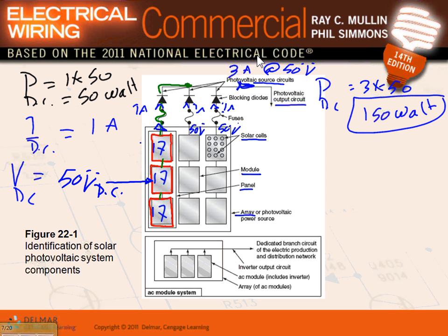Any question? William, does it make sense? Rob, my friend? Okay, now we'll get back to this, how to size it and disconnect it and all this stuff. And I'm going to get back, Dustin, to your question. There are two inverters, guys. One of them is AC inverter, one is DC. The one that you're looking at here is a DC system. The smarter ones, you know what they do? They have a panel that actually has an AC inverter on it. So they have an AC module system. Each one of them has an AC module on it, and they convert at the AC level.